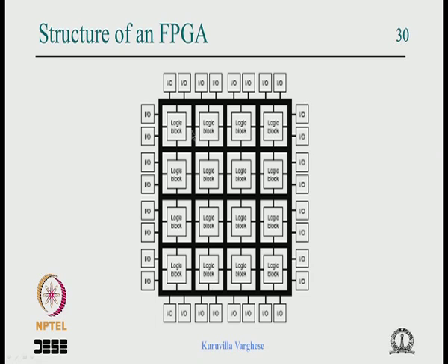In principle, how the design is done in an FPGA is that the synthesized logic is placed across multiple blocks depending on some constraints. An IO pin can be connected to the input of a logic block, and that output can come here. Maybe it can be taken to the input of this logic block, as well as come all the way to this logic block, and this output can be taken to the input of this logic block and so on. So this structure allows a lot of possibility of connection, and you can see that it's not a single switch like a CPLD.